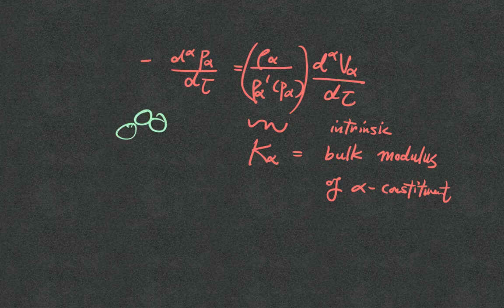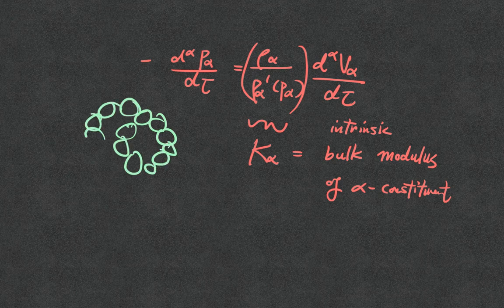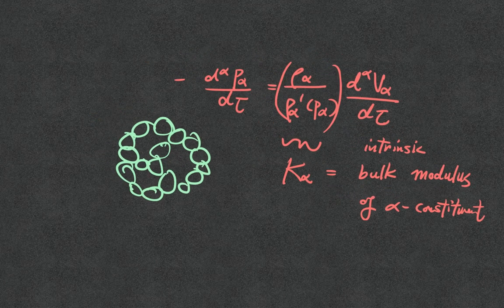I have those particles. Let's say I have this porous media with 3 pockets. And then the representative volume, I will draw a circle to represent this RVE. Okay, this RVE can be compressed or extended easily because there's a pocket here that has nothing but gas. Now, I can change that circle easily without changing the size of individual grain or water.